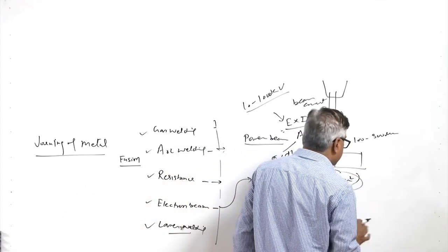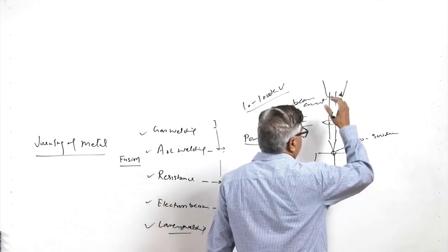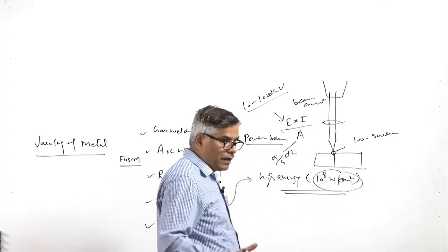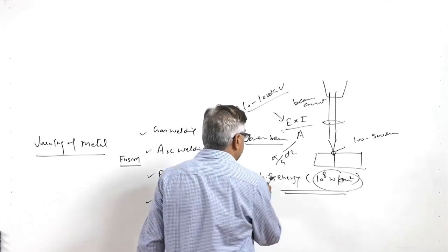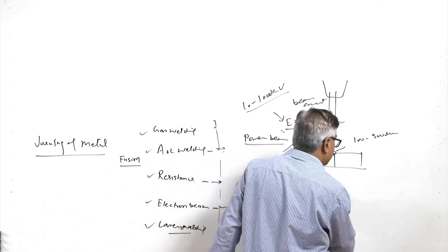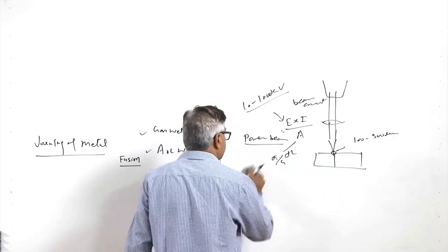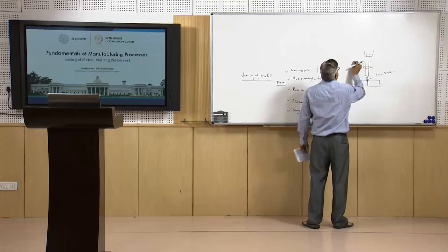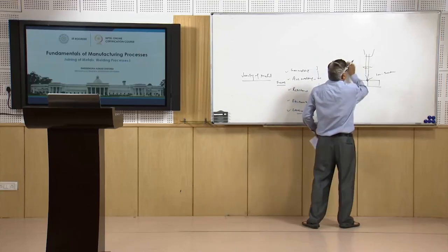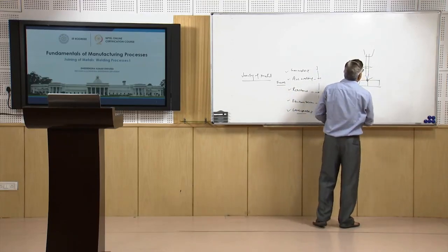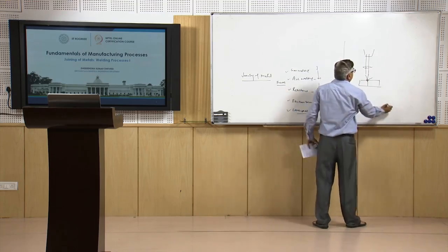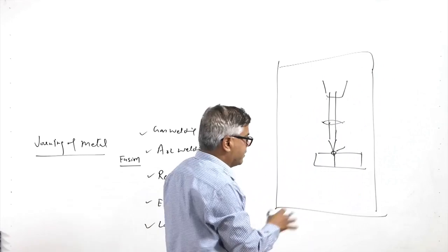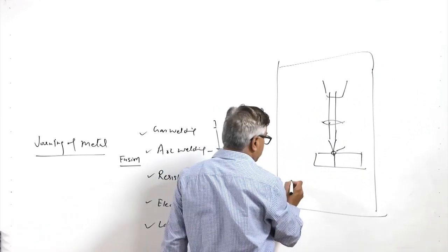Since the beam is of electrons, when traveling through the air they collide with the atmospheric molecules, and their speed is very adversely affected. They lose their energy in the course of traveling in atmospheric conditions. So it is always preferred that electron beam welding is performed under vacuum conditions. The entire system of the beam and the workpiece table travel system is enclosed in the vacuum.